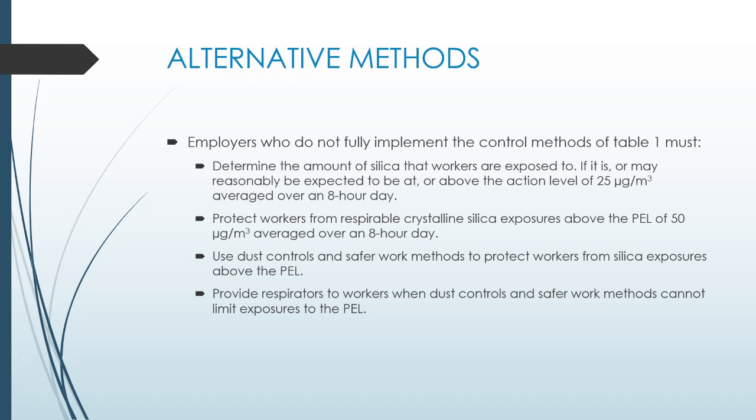If it's above the PEL, or permissible exposure limit, of 50 micrograms per cubic meter, we have to protect you guys. We have to give you the PPE and the HEPA filters and everything else, and then use dust controls and provide respirators. The difference is we have to do a lot of the legwork. We have to do a lot of logistical things while using alternative methods. It just makes sense to use Table 1.